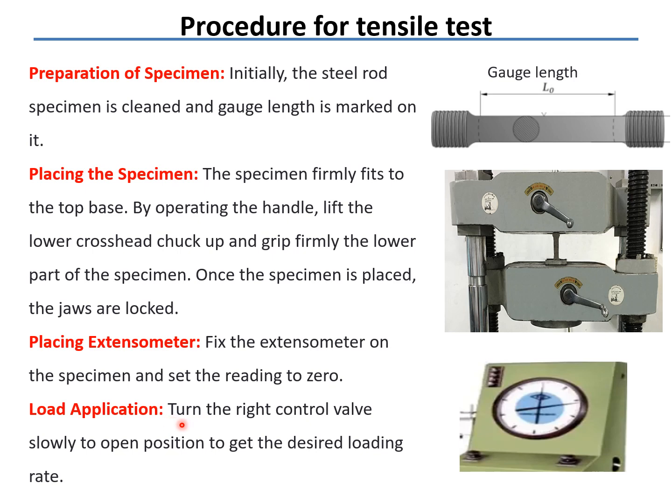And the last is the load application. So with the help of the hydraulic pressure, we give the load to that specimen. It means we apply the uniaxial tensile force, and with the help of this pendulum dynamometer we can also record the applied load.